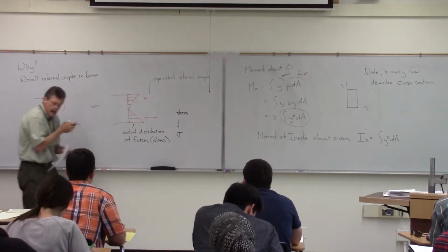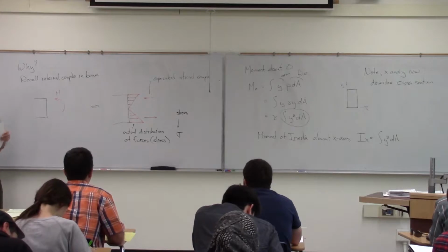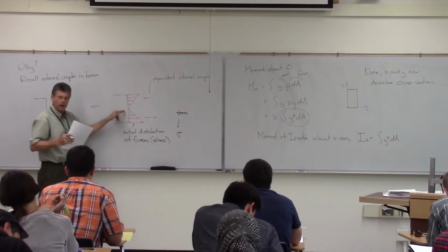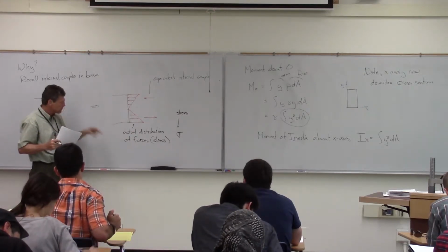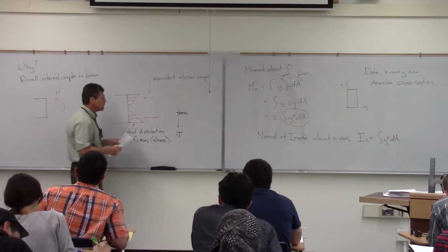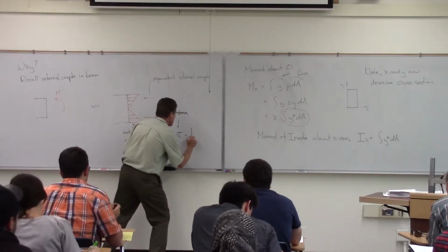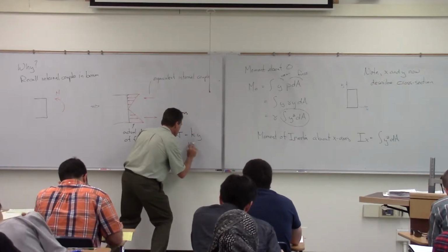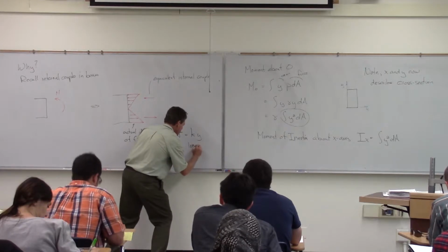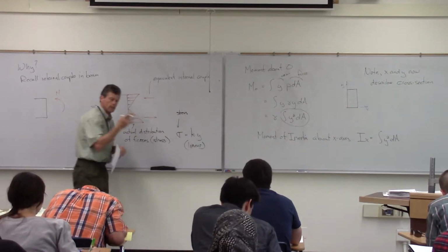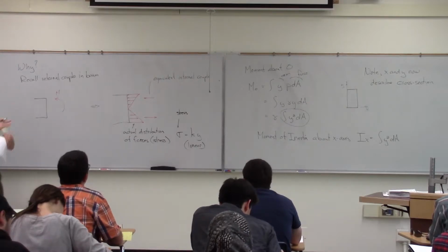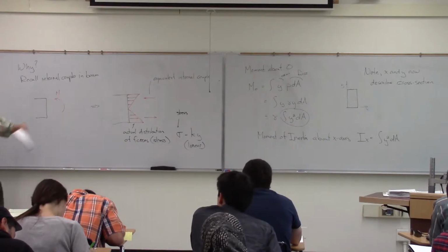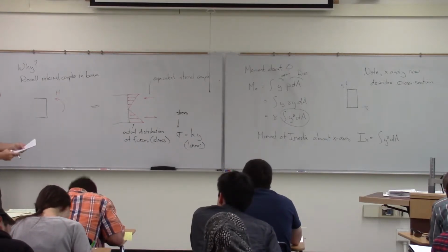So what we're going to see, this actual distribution of these forces, it looks like a distributed load on a beam like we've done before. But again, stress is going to be across an area now instead of across a length. So hence the term stress. The word stress then basically is going to be describing this internal force that's going on, but it's going to be describing it across the area of that cross section that we've cut out there in terms of x and y in that direction there.